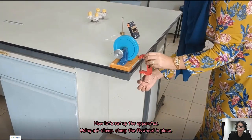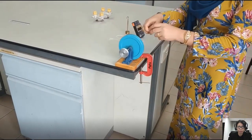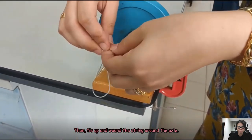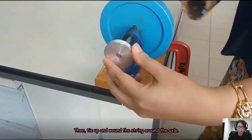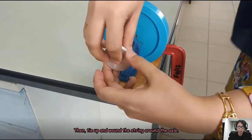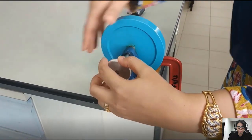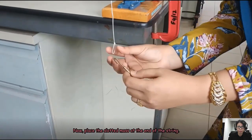Now, let's set up the apparatus. Using a G-clamp, clamp the flywheel in place. Then, tie and wind the string around the axle. Now, place the slotted mass at the end of the string.